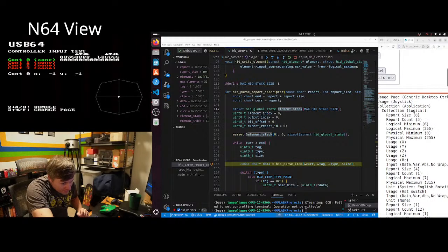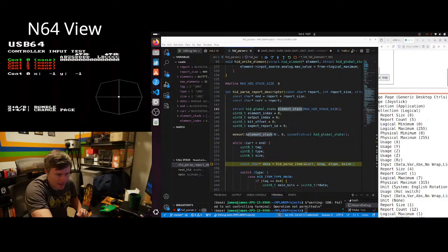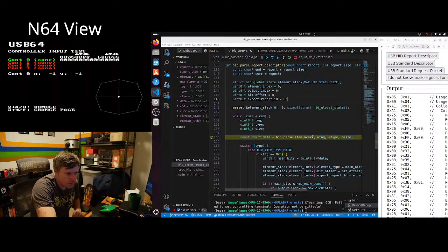If it were me, I would have made it go from negative 128 to 127, or negative 127 even. That just would be easier to interpret, but I can make that work. Actually, I think I designed my driver to handle that. It should recognize that it doesn't go negative and put the center point in the middle of these two values. Hopefully.